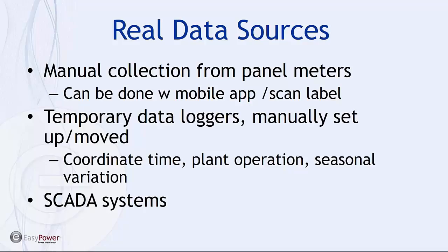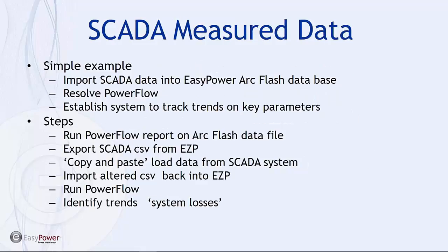So what I'm going to do next is march through a process that can be done either by the consulting firm or taught to a facility manager or a maintenance team, to take the SCADA measured data, import it into the EasyPower data file, and again, garner the benefits of doing a power flow analysis with real data.